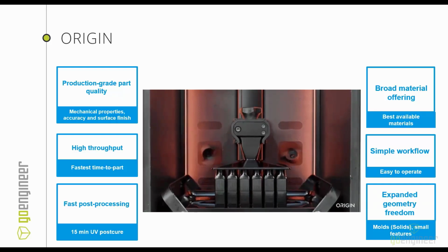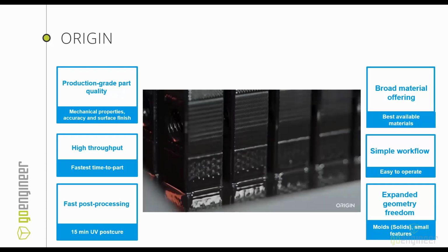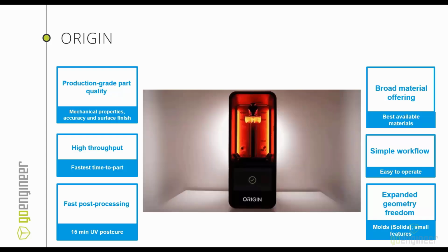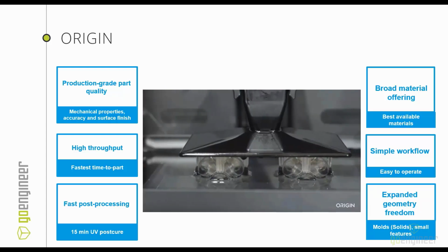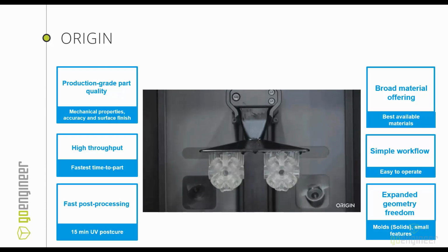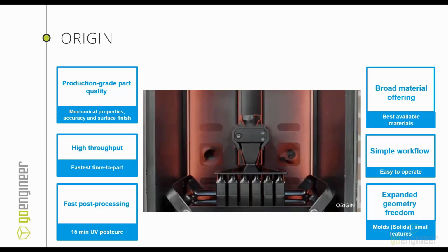You can actually change out materials multiple times a day if you want, and it becomes a much more economical process than, say, stereolithography, which we can also do and can also run a Perform material. But that just generally has a higher startup cost, and with stereolithography, you're not changing materials. You have your one material you dedicate to pretty much, and that's the one you're going to be running.